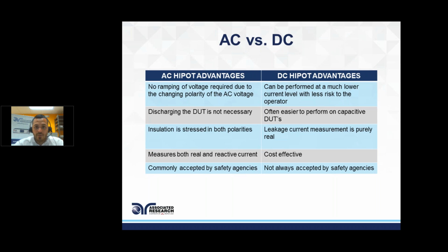But a DC Hipot's advantage is that it's cost effective, right? They're usually single box, one type of test, and easy to move around from test station to test station. But again, they're not always accepted by safety agencies. Now that's from standard to standard. Again, not always doesn't mean the majority. The majority of standards, I think, will allow you to test in DC if AC keeps failing you due to that reactive current.